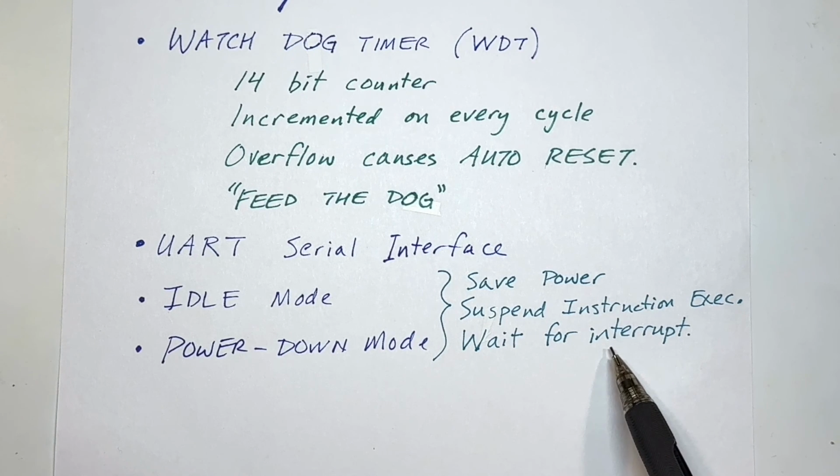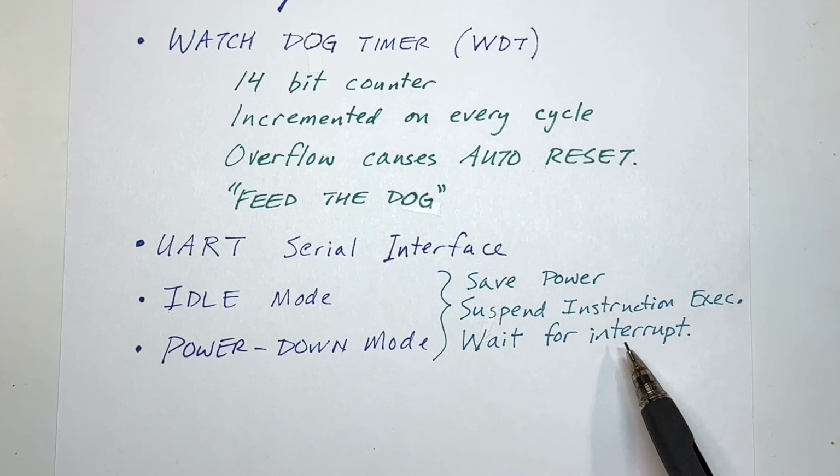I'm sure there's other things about the 8051 chip that I haven't covered and maybe that I don't even know about. For example, I didn't really discuss how the pins work, and in particular how the external memory works. But basically there's an interface so that the chip can send out addresses and data or read data from the external memory that you might also want to know about if you intend to use external memory.